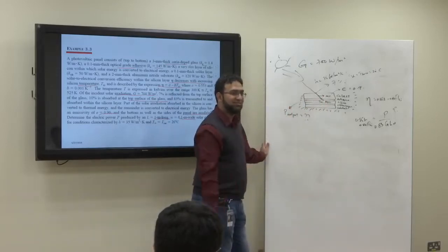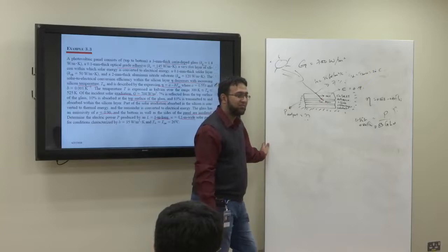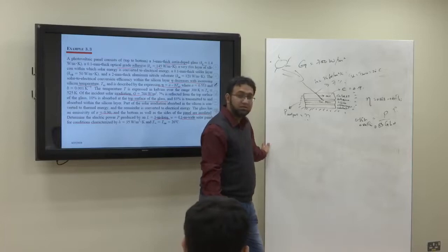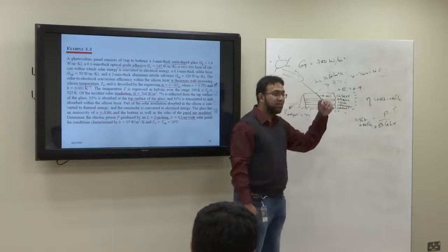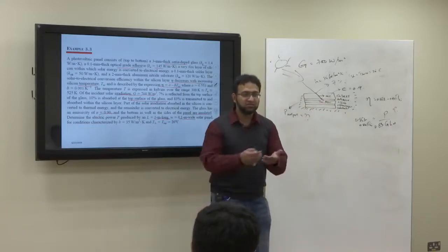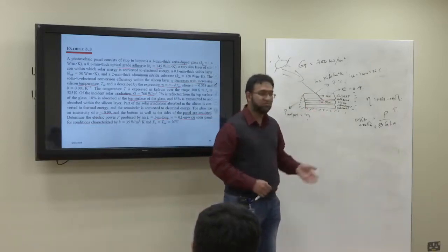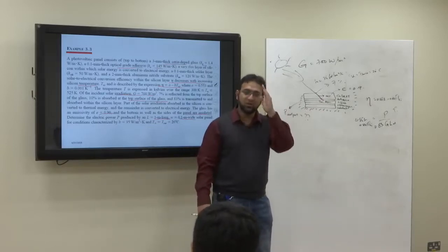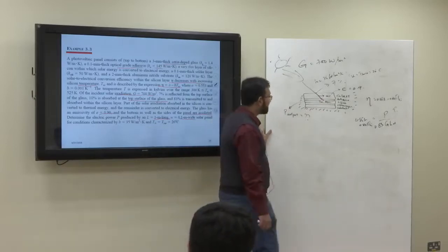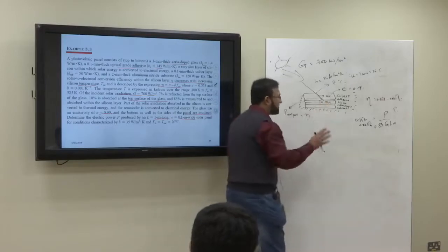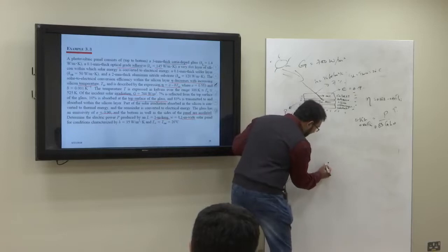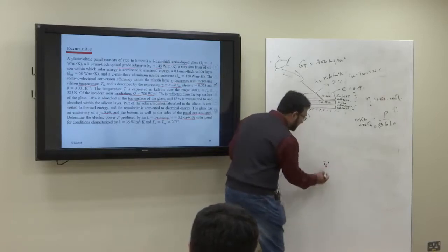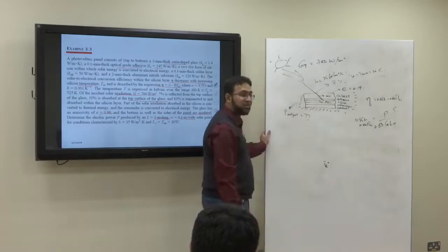So the last layer the heat will touch is the silicon, where it will be absorbed. The thing is that below the silicon layer, heat cannot flow, since there is insulation after the substrate. The only way heat can flow is going up. So the layers below the silicon chip are useless for us. We'll consider the silicon chip as the last layer for our consideration, and this is T_Si. T_Si is what we need.